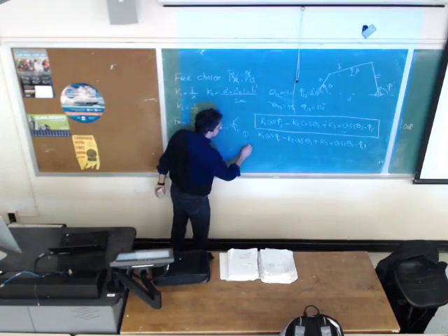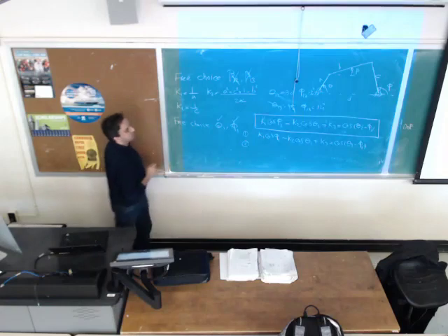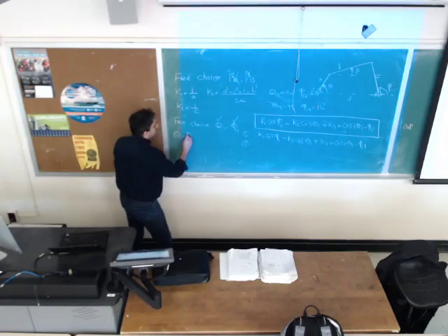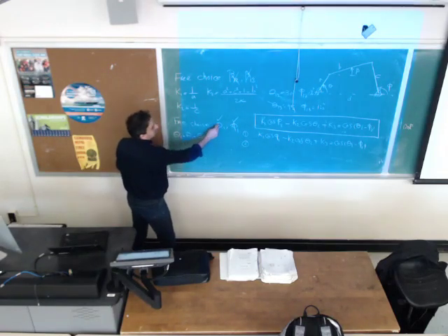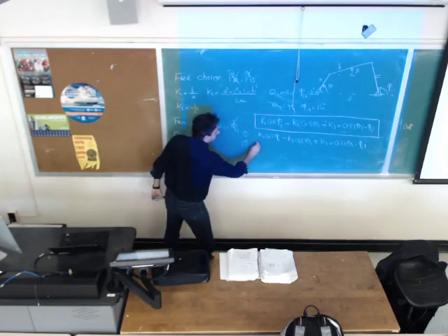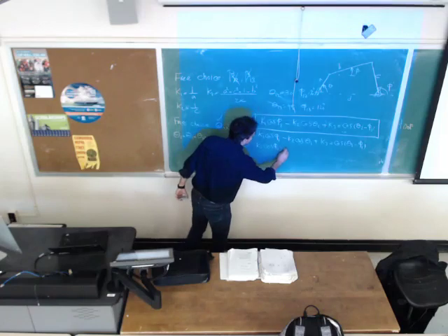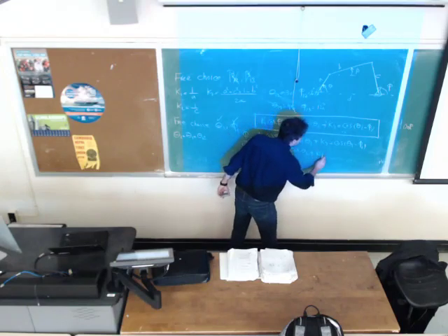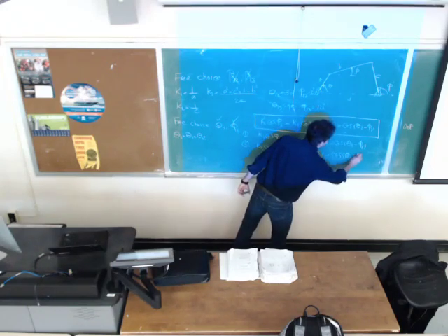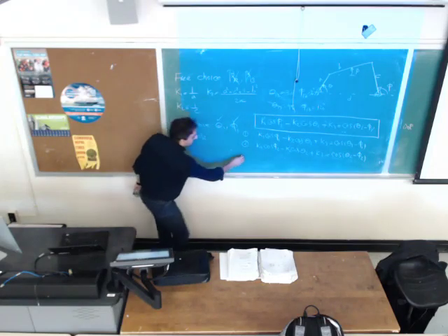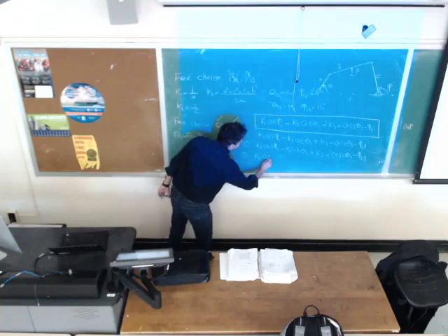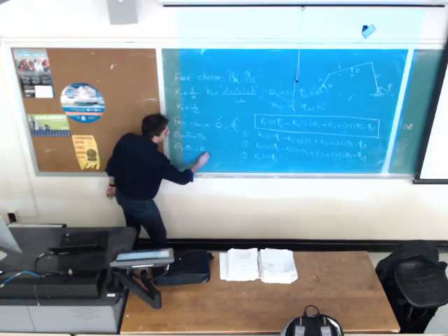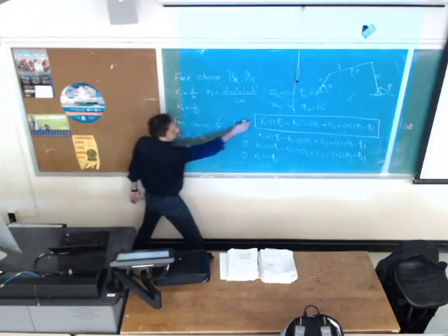First precision point. Second precision point, phi is going to change to phi 2, theta 2 minus phi 2. What would be theta 2? Theta 2 would be theta 1 plus theta 1, 2. Theta 1 is a free choice, theta 1, 2 is given. So I'm going to have k1 cosine of phi 2 minus k2 cosine of theta 2 plus k3 equals cosine of theta 2 minus phi 2. And the last precision point is going to be k1 cosine of phi 3. Theta 3 is going to be theta 1 plus theta 1, 3. Theta 1 is the free choice, theta 1, 3 is given.